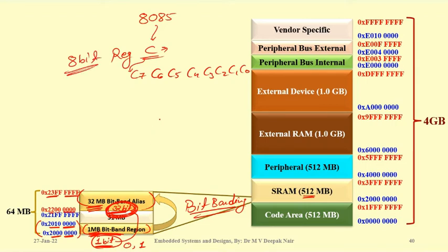So this 8-bit register has got C0 to C7. Was there any instruction which can just make this bit 1 and the rest of the bits zeros, only change one of the bits? Was there any instruction which can take this kind of bit-based instruction? No, for that you are using the whole register, right? So it is not a 1-bit instruction. It is an 8-bit instruction. It is going to change the whole register in total, right?